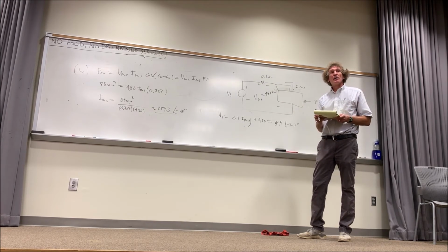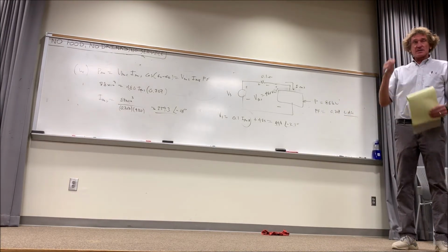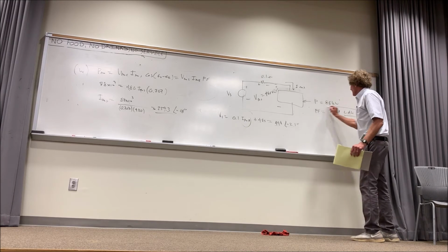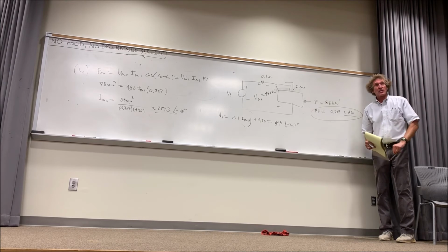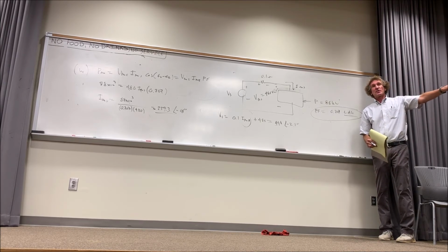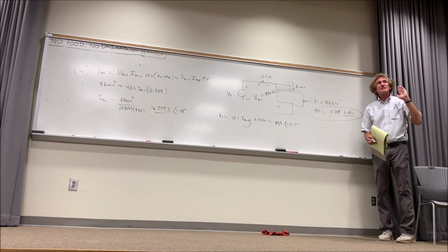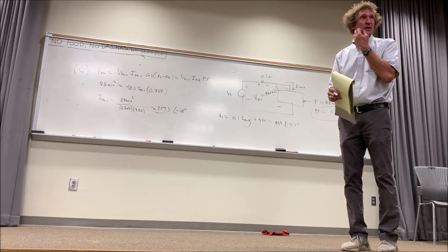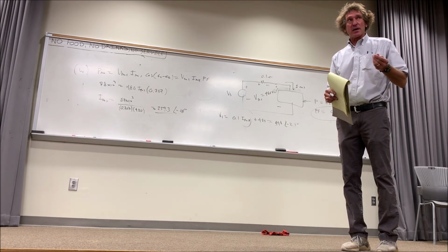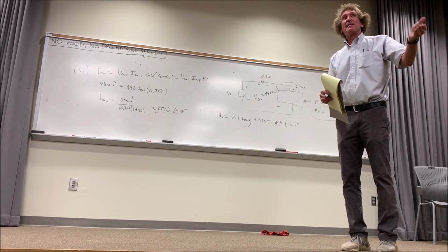Now, I know you said I spaced out, what was the negative 45, where did that come from? I said that the power factor is lagging and it's 0.707. Lagging means the angle will be negative associated with the current if the angle of the voltage is 0 degrees. This is almost always the way it's done. Follow me? Just let me finish this. I know we got a test coming in here next, but if that's the case, that's the voltage. Now listen to me carefully. What power companies do is incentivize, not your residential areas, but any kind of industrial complex that uses a lot of power. If you don't have a power factor above 0.9 or 0.95, they start fining you.